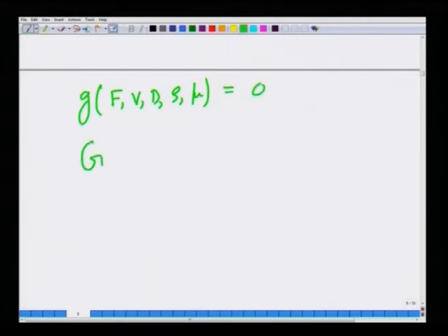We have now reduced it to a functional relationship between 2 non-dimensional groups, mu by rho V d. Now, one important thing is that it does not matter whether, so let us call this pi 1.